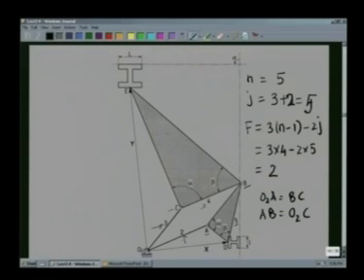Not only that, the triangle ABD and the triangle BCE are similar, as indicated that this angle alpha is same as this angle alpha and this angle beta is same as this angle beta. So these two triangles, namely BCE and ABD, are similar. Now we can show that the movement of the point D and the point E will be very similar. That means the movement of the point D will be copied by the movement of the point E. Accordingly, E will also draw a similar figure as D. The only change will be the size and orientation of the figure.